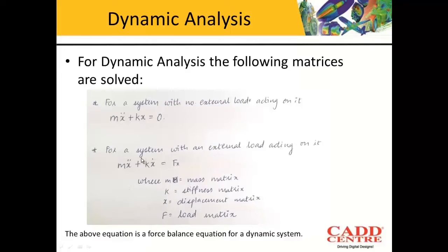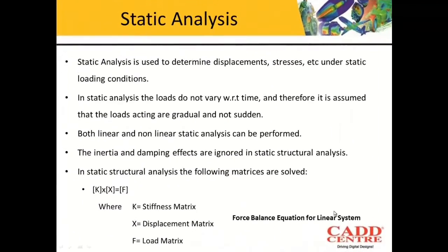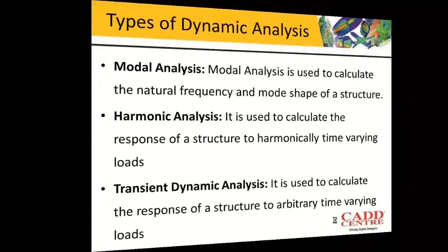But if the system that you are analyzing has an external force acting on it, then the equation that is solved by the software is m double derivative of x plus k x is equal to f of x, where m is the mass matrix, k is the stiffness matrix, x is the displacement matrix, and f is the load matrix. This equation is a force balance equation for a dynamic system. Earlier what we saw is a force balance equation for a linear system. That is the main difference between static analysis and dynamic analysis.